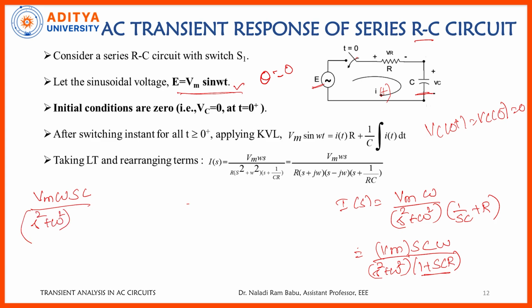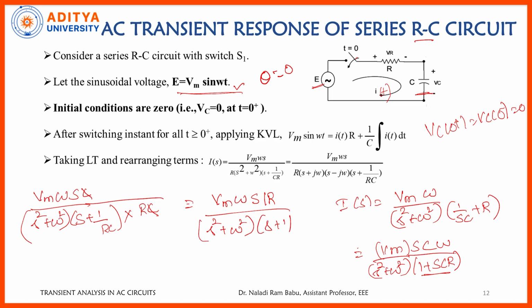If I take RC common, it will be s plus 1 by RC into RC, because we have taken RC as common. Therefore, this C and this C get cancelled. Therefore, we got the solution as Vm omega s by R divided by (s square plus omega square) into (s plus 1 by RC).